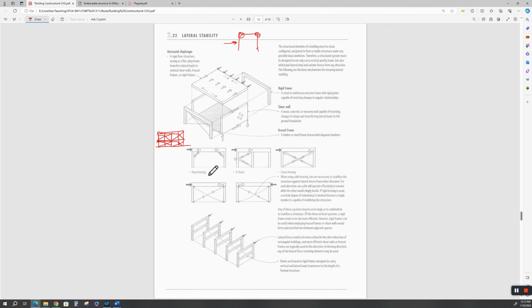All right, so bracing. We got all kinds of bracing. We have knee bracing. And what do we mean by that? Well, here's the knee, bent knee, right? That's a knee bracing. All right. Force on the frame goes this way. What does the knee brace do? It stiffens it, right?